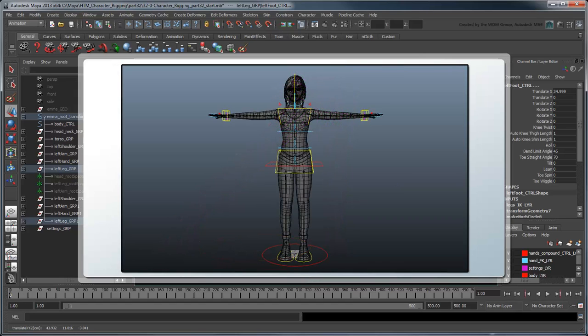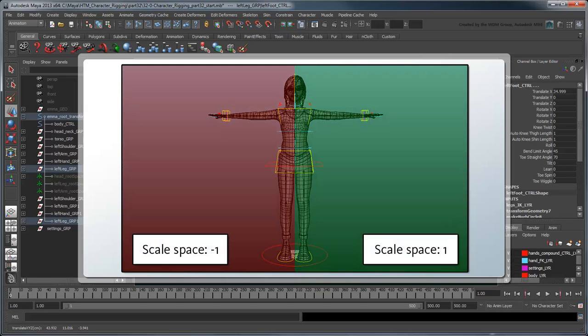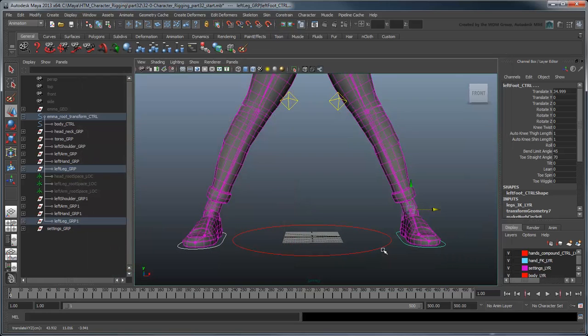This is symptomatic of a larger problem, which is that the controls and joints exist in mirrored spaces. We can't fix this by freezing the mirrored controls transforms either, because it would impact all the connected nodes that drive things like joint scale. So what does this all mean? Unfortunately, it means there's no easy way out, and we actually have to recreate the right leg and right arm rigs. It's the only way to guarantee everything will act predictably in the space we want. Before you pull up your sleeves once again, we have some handy tips and tricks you can use to make the process less painful than the first go-around.